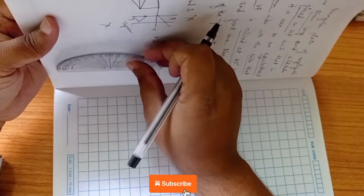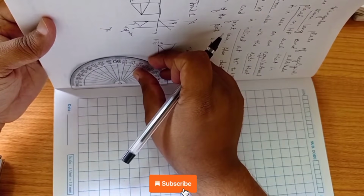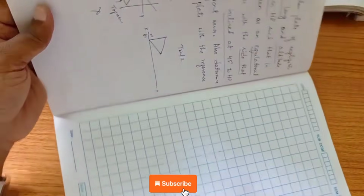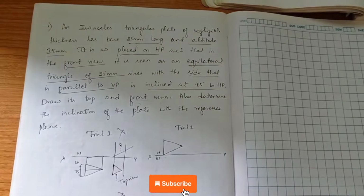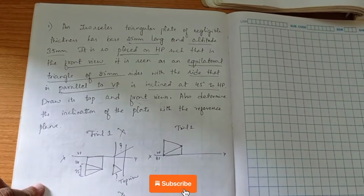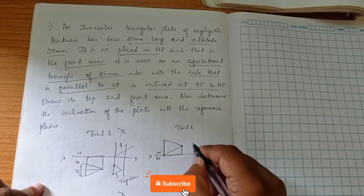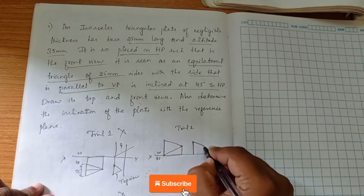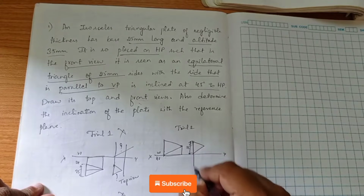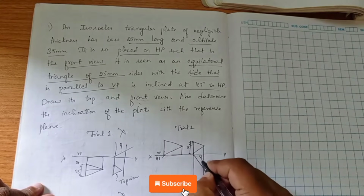So the equilateral triangle is in the vertical plane, but one of the corners is touching the XY line. Say this is the front view, then projecting downward we get the top view. Now in this position they have not mentioned the second angle of inclination, so we have to construct an equilateral triangle of dimension 25 here. Then by taking this length, we can find out this angle of inclination.